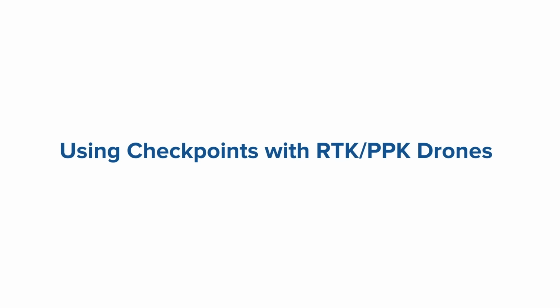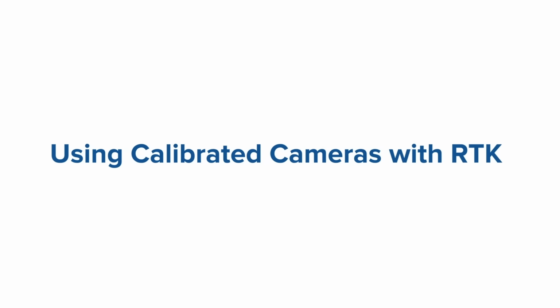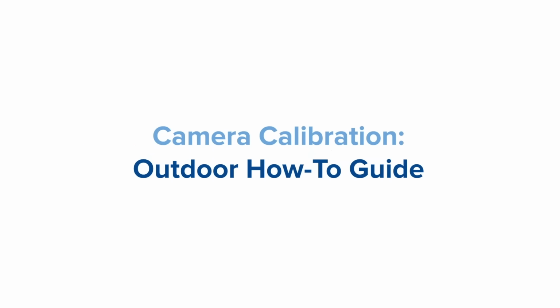All right, so checkpoints. I'm actually going to show an example of this on a live demo at the very end of this presentation, so I won't go into it. But the next thing is, regarding this vertical bias, using a calibrated camera. RTK is going to give you great consistency over the project. That's its biggest benefit, the consistency you're going to achieve from an accuracy standpoint.